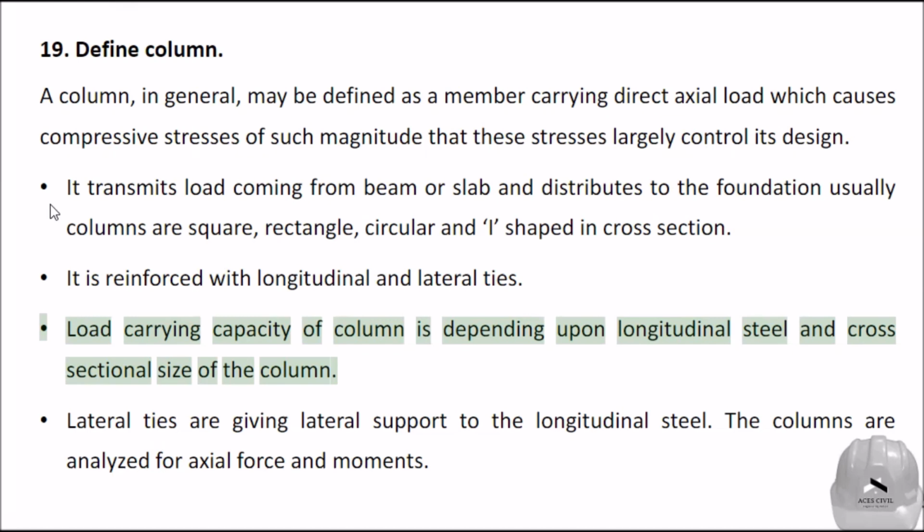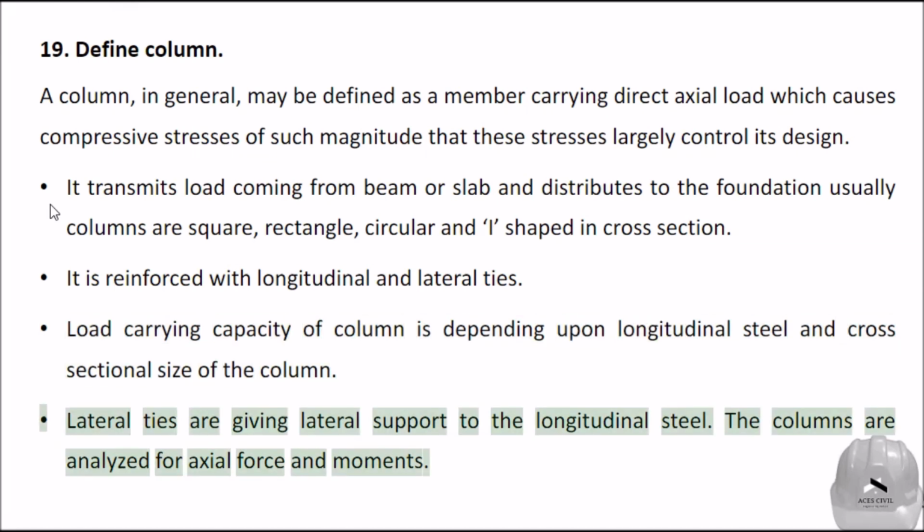Load carrying capacity of a column depends upon the longitudinal steel and the cross-sectional size of the column. Lateral ties give lateral support to the longitudinal steel. The columns are analyzed for axial force and moments.